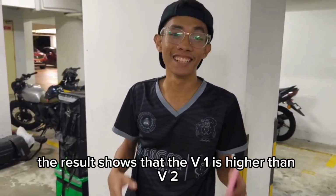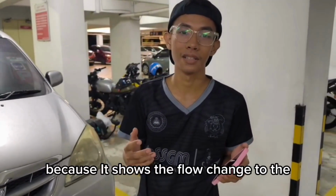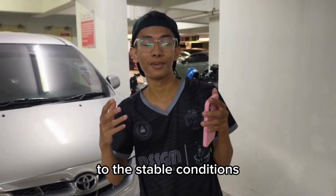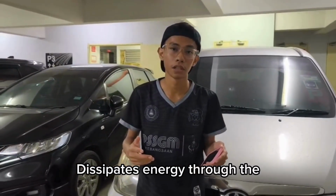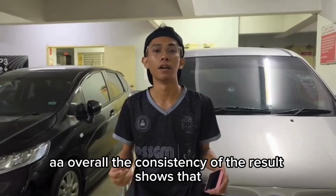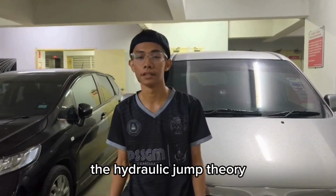For the discussion, the result shows that V1 is higher than V2. That means the water is slowing down after the hydraulic jump. Then the Froude number decreased because it shows the flow changes to stable conditions. Lastly, the energy loss confirms that the hydraulic jump dissipates energy through turbulence and water force. Overall, the consistency of the results shows that the experiment follows the hydraulic jump theory.